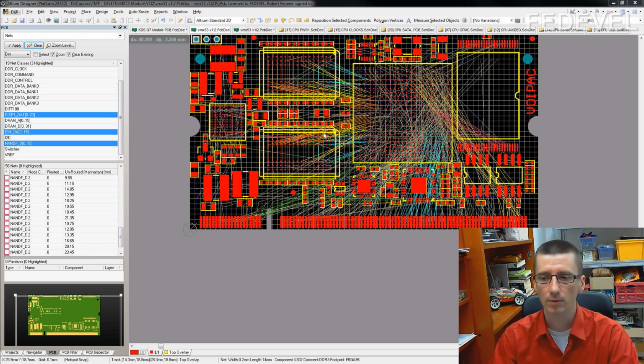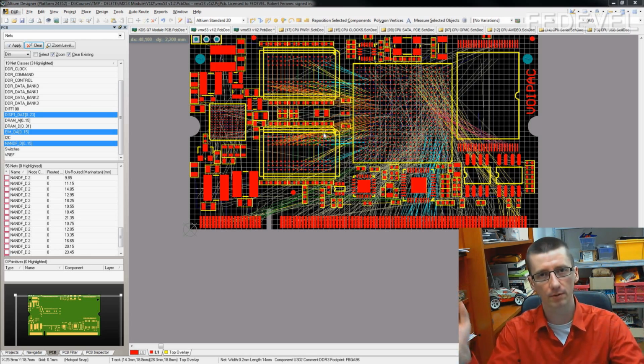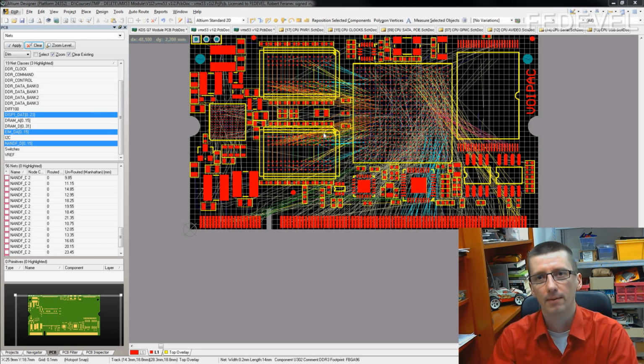Yes. Once you start with some simple tracks and then you limit your layout, it will not be possible to do the connections for very wide buses. So that's the reason why to start with the wide bus. You have plenty of space. But be careful, before you start doing the layout for the bus, we need to do something else. What is it?